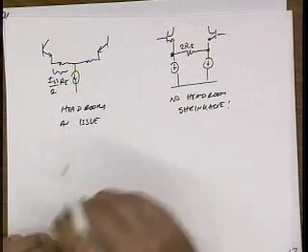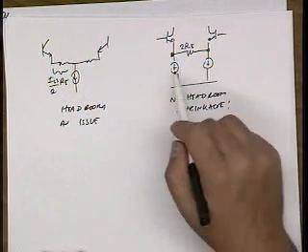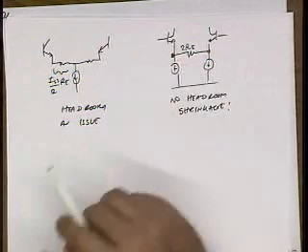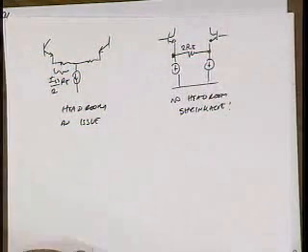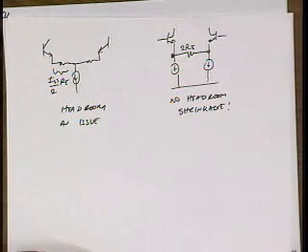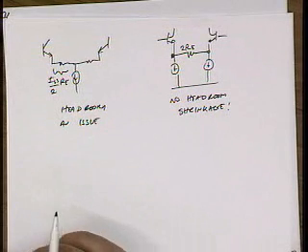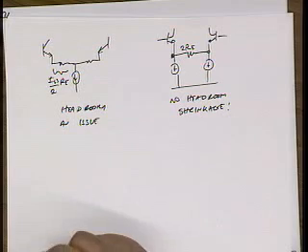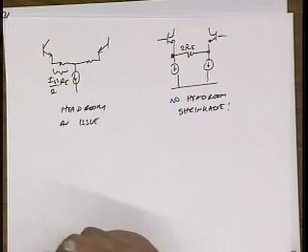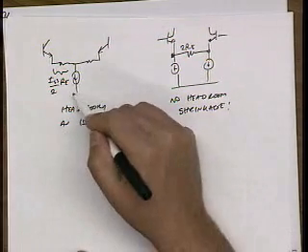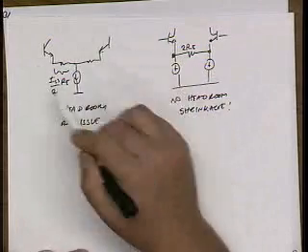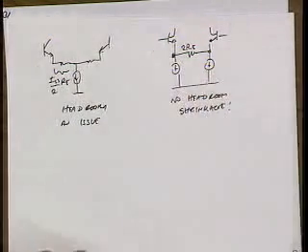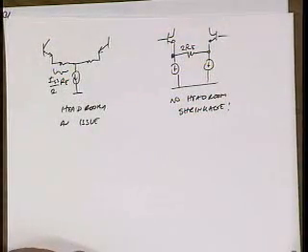Well, you could argue that matching is going to be an issue, right? Because now these current sources have a mismatch, and so I get more common mode, differential to common mode conversion. Okay. What else? I'll give you guys a hint. What if on the test I asked you to calculate the noise of this guy versus this guy? Which do you think has less noise? And why? Why being the key question.